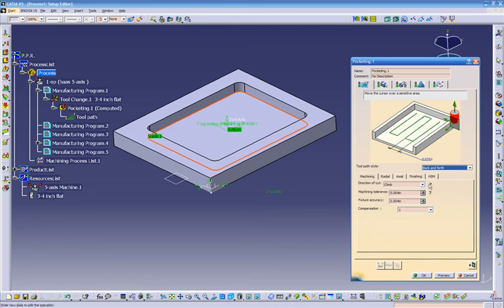See, it's got the little arrow, question mark over here. So if you don't know what this stands for, you just click on this and it'll let you know. See, this is the rotation of the end mill. So the end mill rotates clockwise and it's moving forward this way. See the arrow going this way and the tool rotates this way. So everything is climbing. I'm pretty sure that all the programmers out there know that most of the programs need to be climbing. Rare we find programs that will get a nice finish using conventional. So I very rarely use conventional. I always leave this on climb all the time.